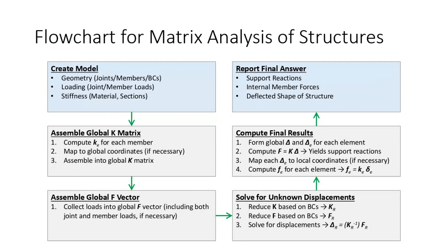We need to understand the loads. And so in RISA, really we're talking about 2 different types of loads. And this isn't just RISA, again, this is just the process. There's loads that can be applied to the joints, and then loads that can be applied to the members. And then finally, we have to define the stiffness properties. We have to define the materials, the sections, all of that. And then once we do that, we hit this little equals button, and the equals button spits out the stuff up here.